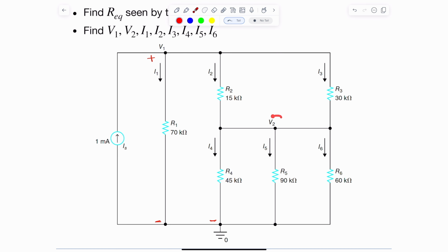All right, the same goes with V2. You will see that this is the plus, and the minus is in here, it's the same. So V2 is the voltage across, for example, R5 in here. This is the plus, this is the minus. So with this notation convention, if you see just V1 at a node and V2 at a different node, there will be somewhere in the circuit a reference node or a ground node. Sometimes it is here, sometimes you can put it in here. It doesn't matter where it is, as long as it is somewhere on the circuit.